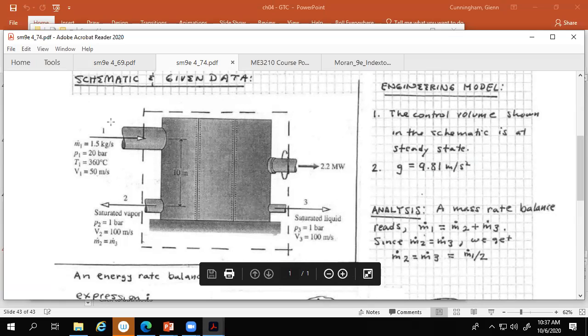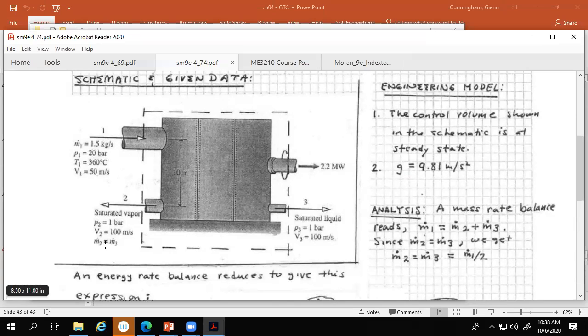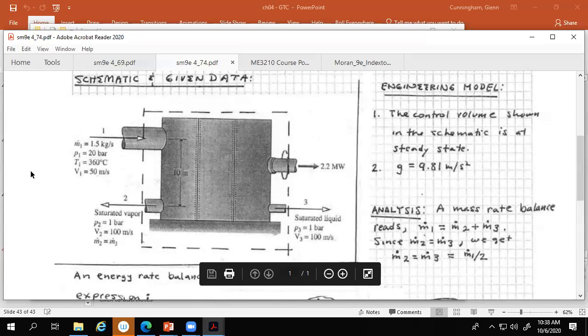So say we have one input energy and we get several useful energy streams out of it. You can have tri-generation, you can have quad generation, but that's the concept. Or they call it combined heat and power, because usually if you're doing this, you have a boiler or something, you're putting fuel in that, and then you get steam, you put it through a turbine, you get electricity, so that's the power side of it, and then you get the heat out of the turbine on the exhaust side and use it out in the plant. So you get combined heat and power out of one input. Cogeneration, same thing.